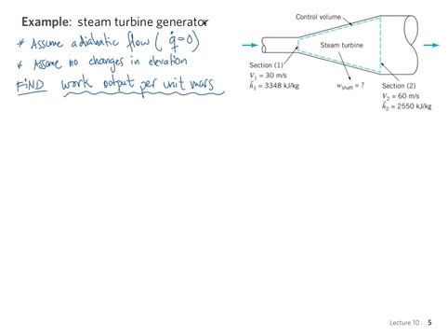The control volume encloses anything that's happening in there in terms of the turbine. We don't have to worry about that. And we have power coming out of that control volume in the form of this rotation, of some shaft that's rotating, and then is probably going to be used to generate electricity, right? So we apply the energy equation.